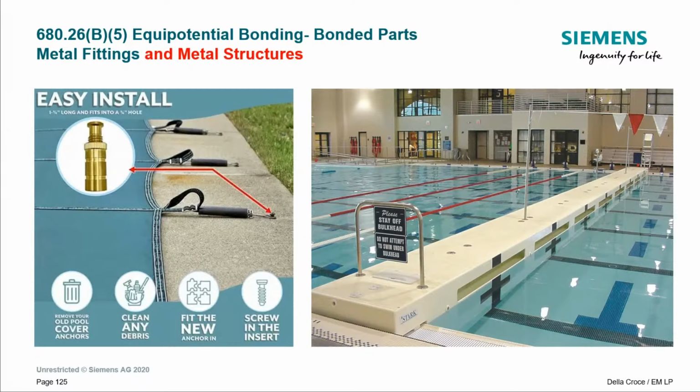And I'm going to invent a product. Here's how I'm going to invent a product, folks. Watch my mouse here. I love to invent products. In this track system, there's going to be kind of a metal grid that's obviously going to be bonded. Although it's not in the perimeter, it's metal and within 5 feet. Either way, it's in 5 feet. Now, the rollers on here are metal or have metal components, or at least a portion of it's metal, so it's always in contact. So maybe just one of the tracks is metal. It has an internal bonding component that runs all the way down inside of this plastic that these all connect into.